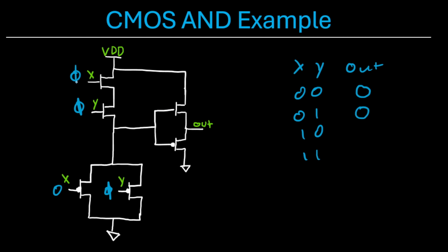Now, flip side, 1, 0. This transistor's off, this transistor's off, this one's on, but again, we need both of these two NMOSs to be on in order for VDD to get connected to this net down here. This PMOS is turned on, connecting ground to this net, which then goes to the gate. This PMOS, again, connecting your output to ground, results in another 0.